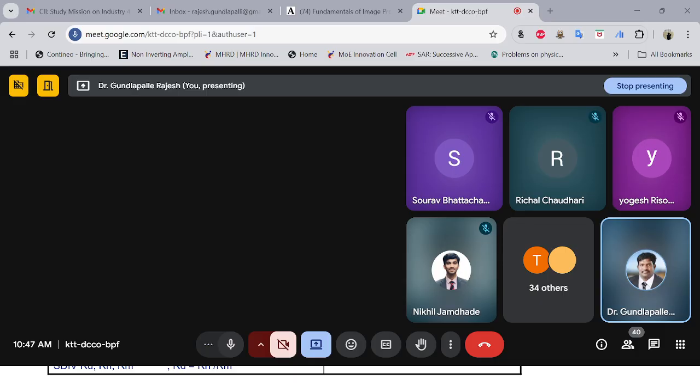Okay, suppose you want to use two operands in the instruction. Of course that is also possible, but the only difference is that the first operand is always your destination. So you can see the difference between the first and second instruction. The first instruction has three operands, where Rm and Rn hold the data. When the contents are added, the result is loaded into RD. In the second case, the contents of RM and RD registers are added, and again the result is updated in RD. So RD means your destination register.